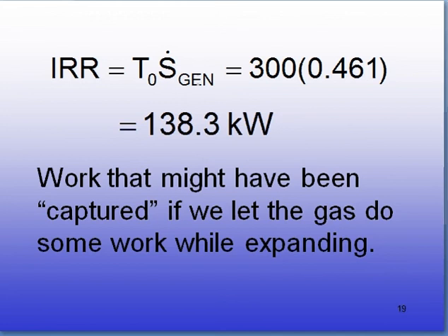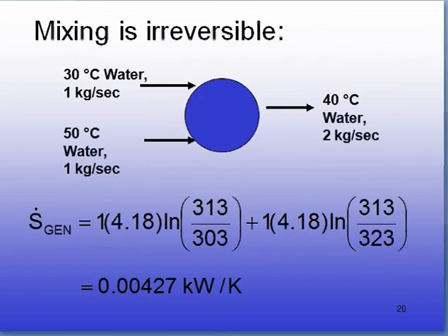The irreversibility of that valve turns out to be 138.3 kilowatts. That's work that might have been captured had we let the gas do some work while it was expanding. So valves are just pure friction. Nothing productive happens in that valve other than dropping the pressure.